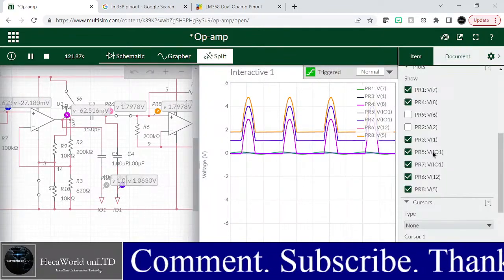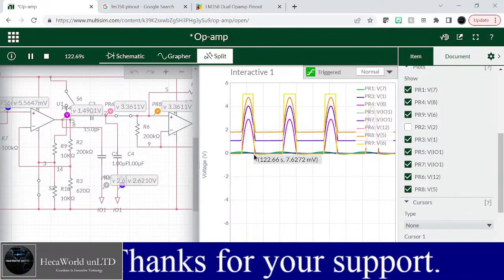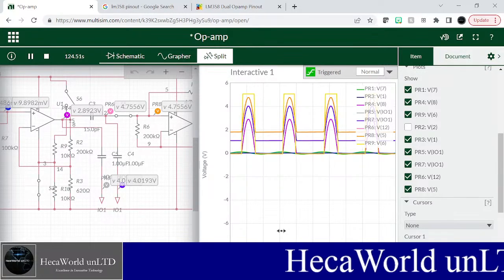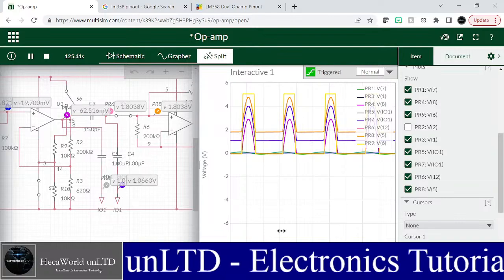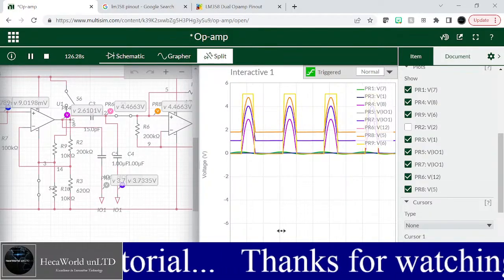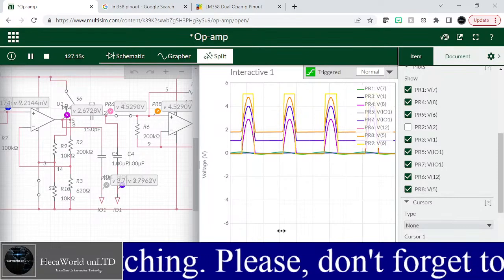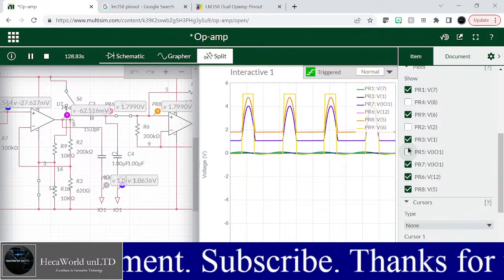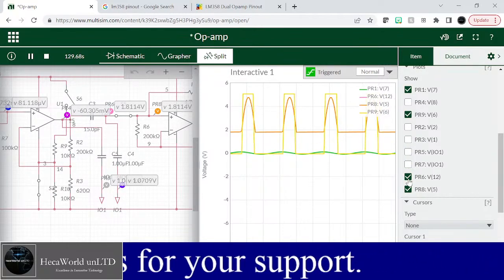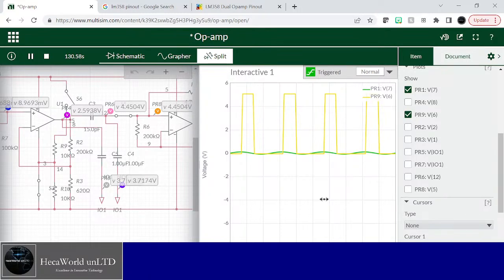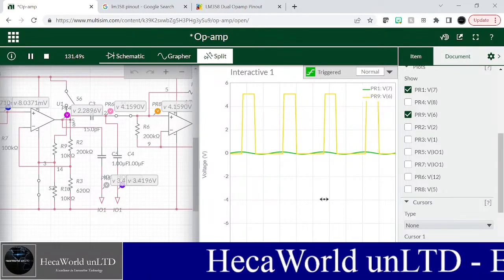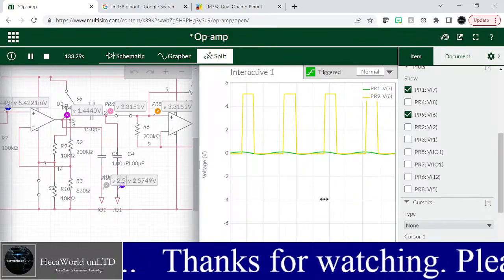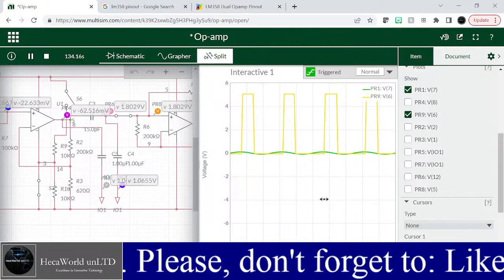Then let's go to 9. You can see how we're debugging this. Now when you go to 9, 9 shows a square wave. This is the output of the Schmitt trigger. So when a signal arrives on the receiver, the output gives you a 1. Remember, the design doesn't have all these probes. The design just has 1, which is the signal from the RF front end, and then 9, which is the signal at the output, the data out of the R433. So it just gives you a 1 or 0 at the output.